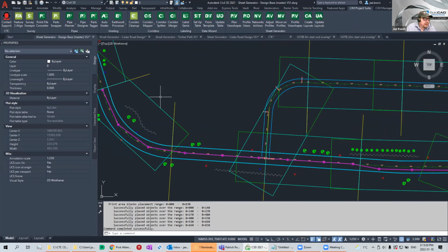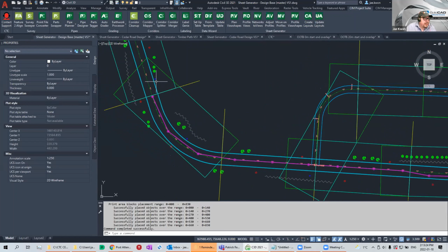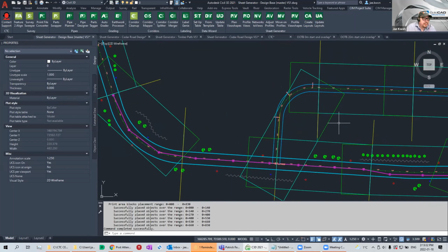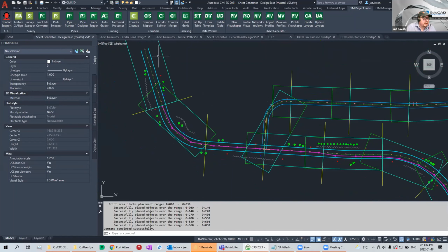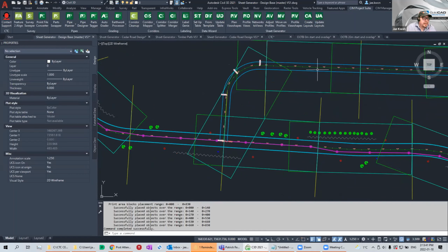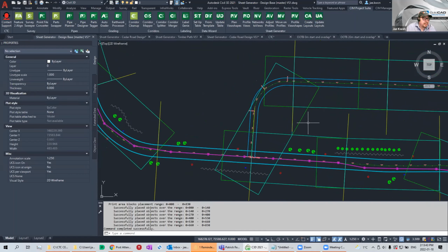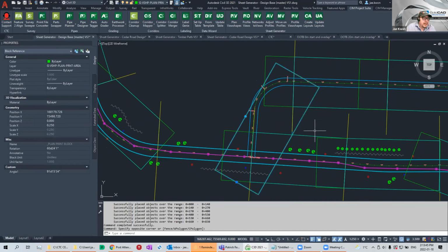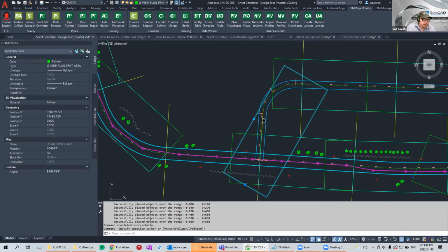These polylines based on a certain layer give us a lot of flexibility on how to set up the sheets, as we've seen a couple of minutes ago, but you do have to watch out, right? The primary road was done with one layer. Now, when you do it with a second road that's connecting to the first, you have to set up a different layer for it to work properly.